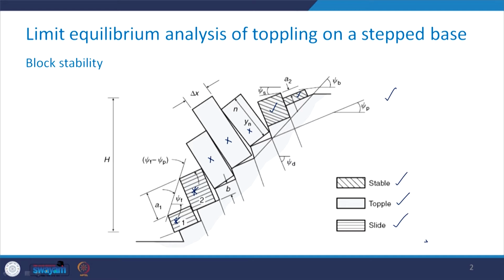And it was assumed that the moment the block at the toe slides, the slope is considered to be unstable. This distance, which has been shown here by B, is constant for all the blocks. These were the assumptions which were involved. And if you recall, we obtained the number of blocks that will be present in such a rock slope, and we represented that as n.